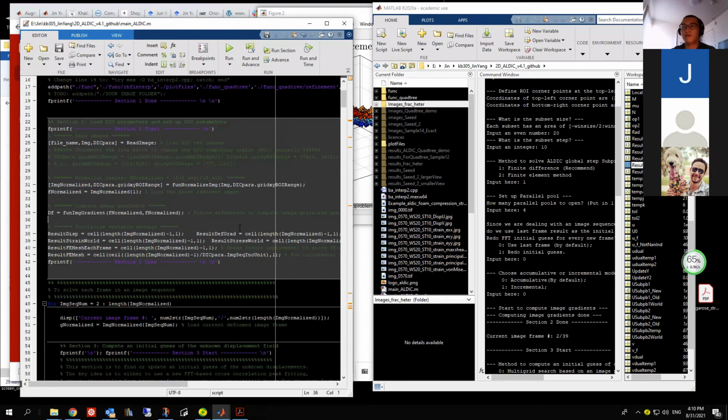Also, this is one of the biggest differences between DIC and PIV. For DIC, because in solids we care about the strain or displacement, we are always in the cumulative mode. But for PIV, you care more about the velocity or vorticity, so you always just compare two frames. So actually, DIC is more challenging than PIV in some way, because in PIV you always compare two neighboring frames, while in DIC all the much later frames still compare with the first frame. Right. Okay.